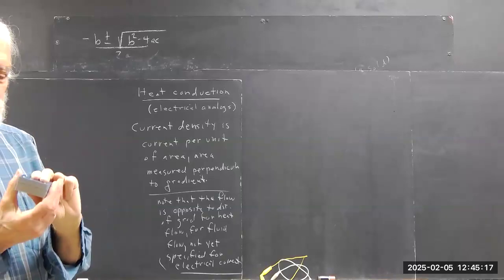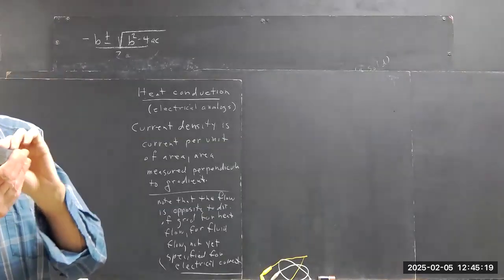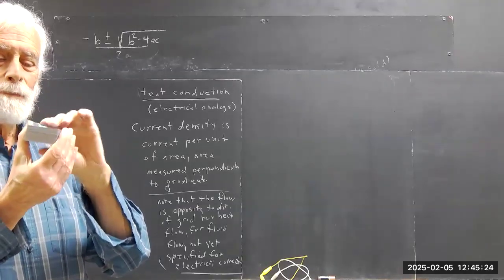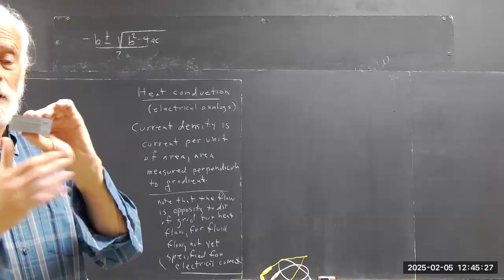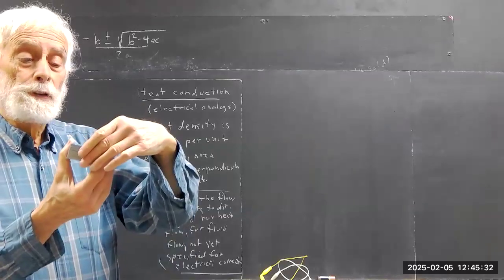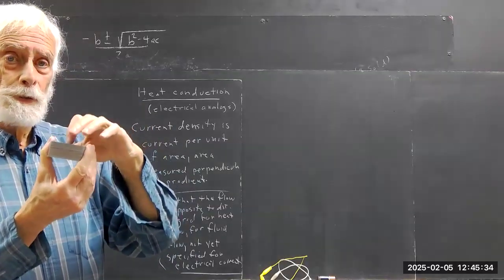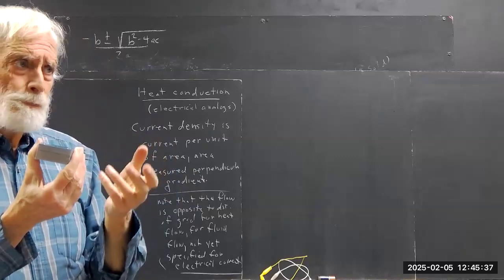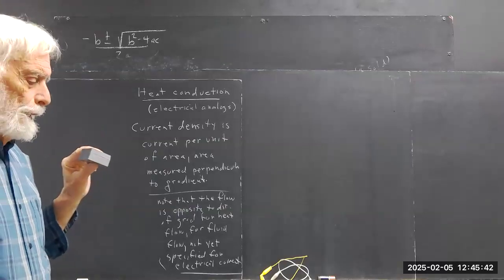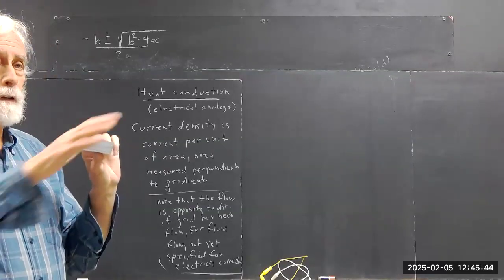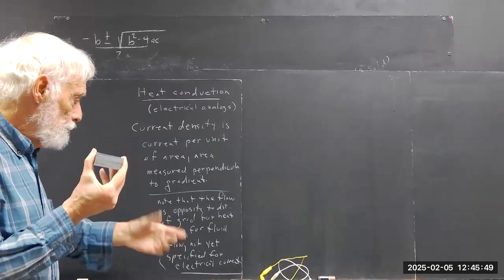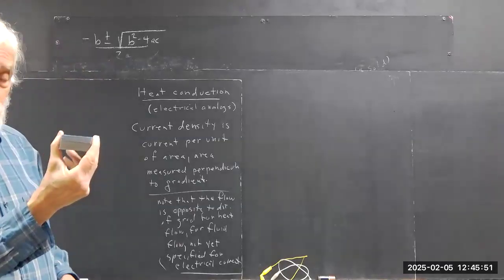Okay, so we have that heat flow. Now we're ignoring the fact that we're losing a little bit of heat from the sides of this thing. Mainly we're ignoring that because we had this thing insulated by styrofoam all the way, about a half inch of styrofoam. It's not going to lose much to start with. It's mostly going to be from the upper surface, but it'll be appreciable. But if we put the styrofoam around it, we pretty much ensure the linearity of our graph, temperature versus position, and everything else. Okay, well, that's a lot of background, but those are the things we think about here.